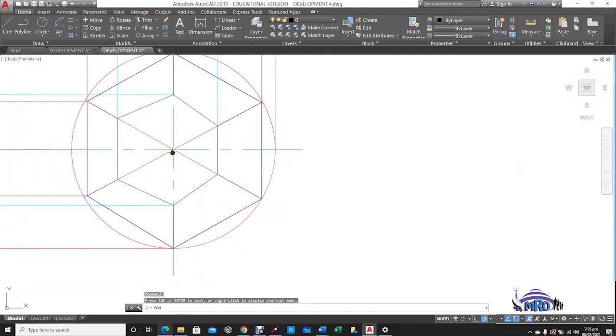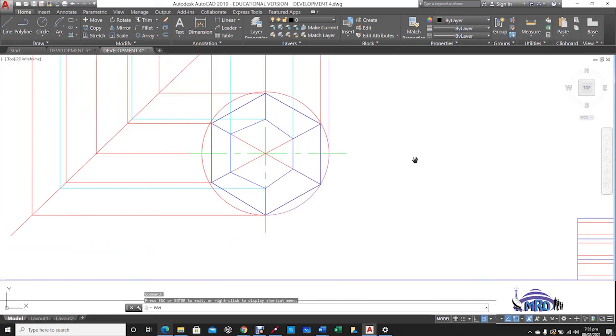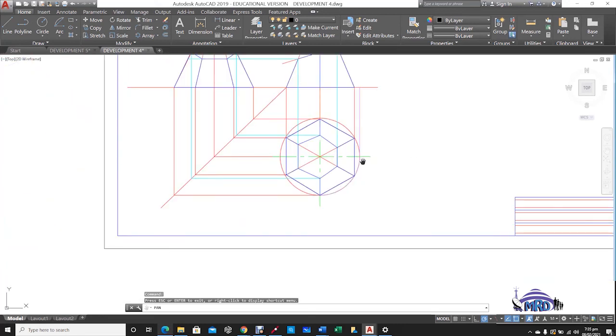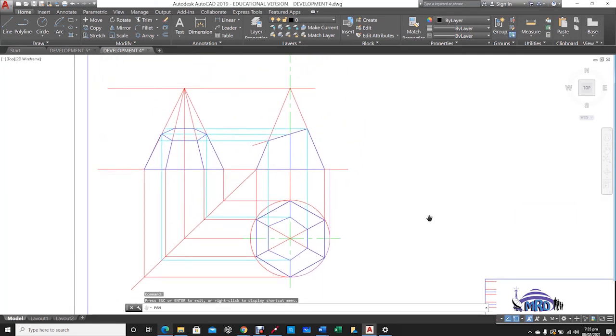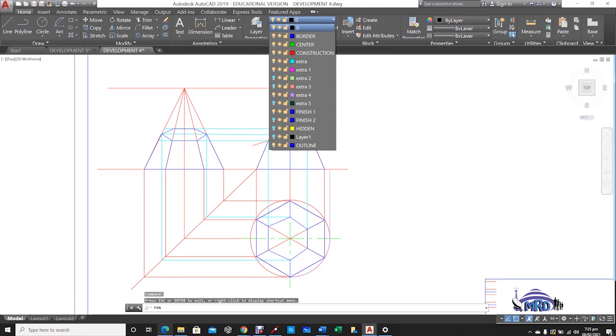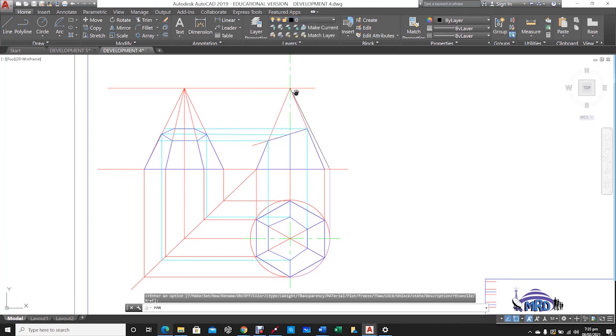This purple curve represented... And if you continue to look, then you will see that where that has touched the center line, I've carried a vertical line up to the base of the front view. Having gotten that line to the base of the front view, I am now able to draw what we can call the true length of a side for this drawing. So this line now represents that true length.